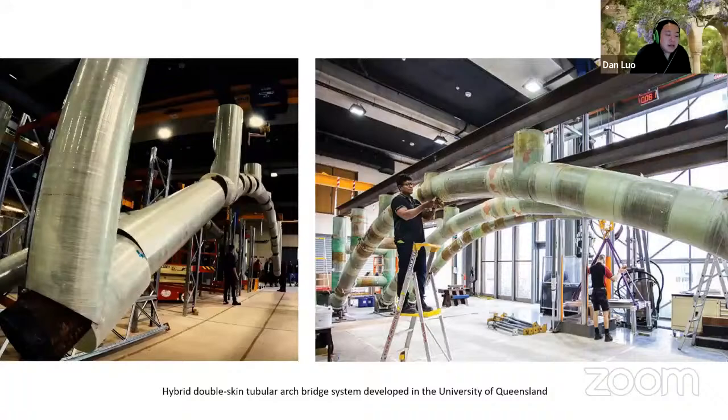So the way to connect them is basically for workers to wrap up the joints. The tube itself also serves as a reinforcement to the cast member. After joining the FRP tubes, they cast the gap in between with concrete. This is something that industry is already using.